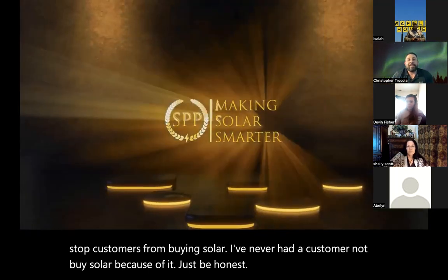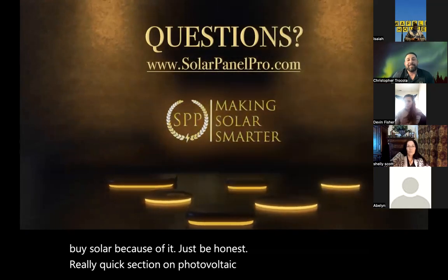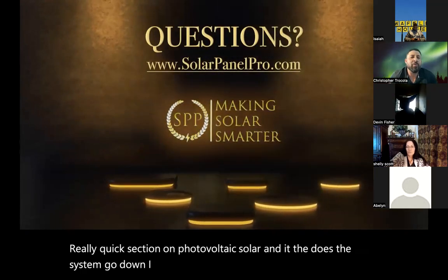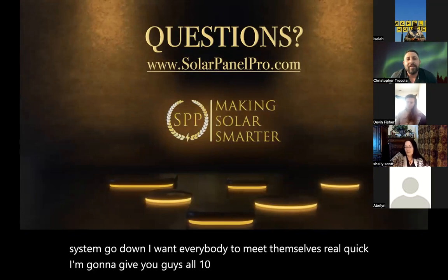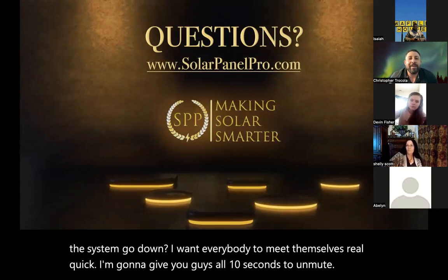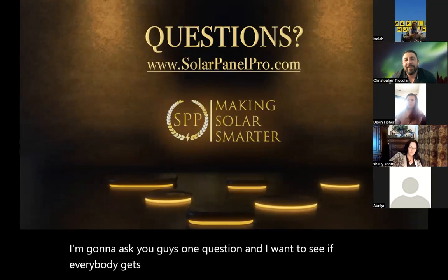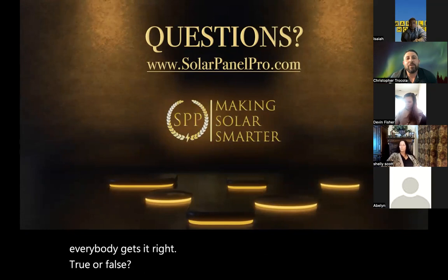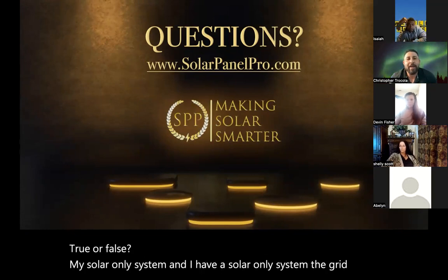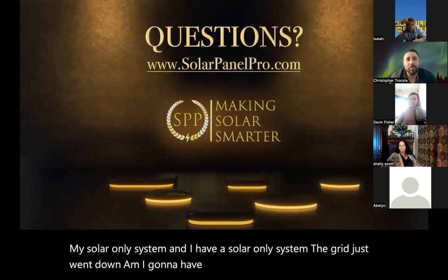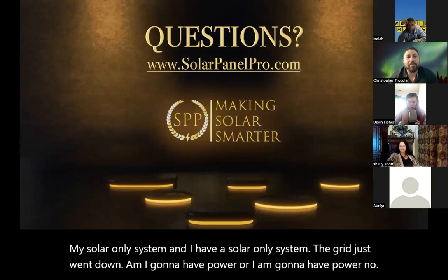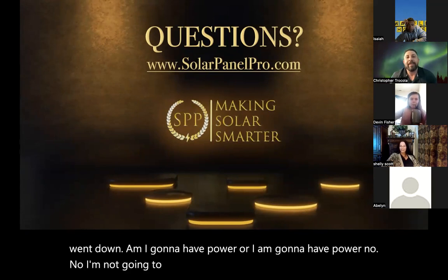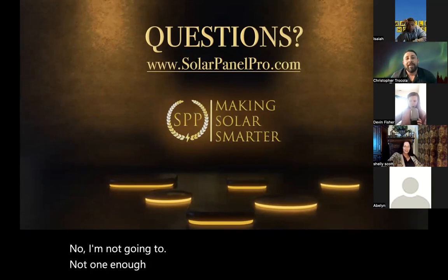Really quick section on photovoltaic solar and does the system go down? I want everybody to mute themselves real quick. I'm going to give you guys all 10 seconds to unmute. I'm going to ask you guys one question and I want to see if everybody gets it right. True or false? I have a solar only system. The grid just went down. Am I going to have power? No. No, no, no. I'm not going to have power. I can't say that one enough. You're going to kill somebody. Yeah, that's exactly what would happen.